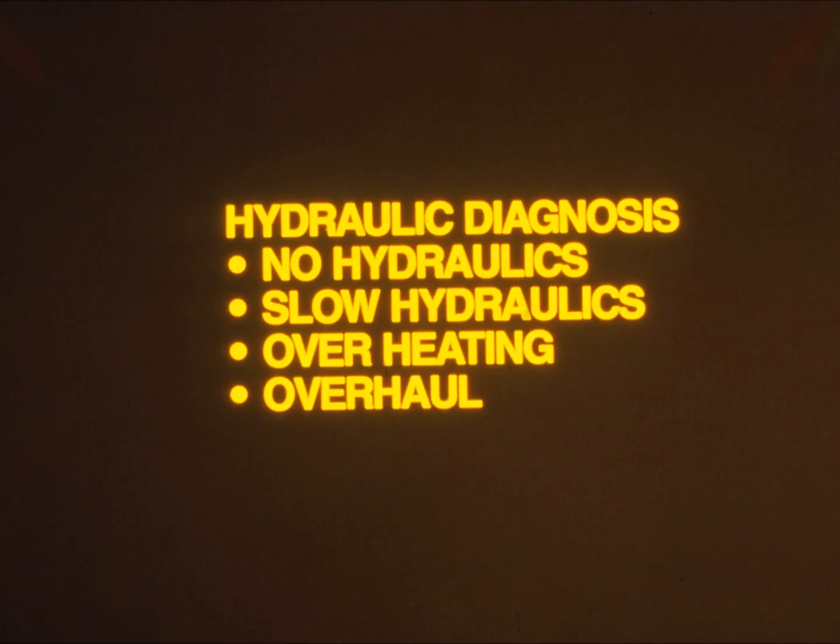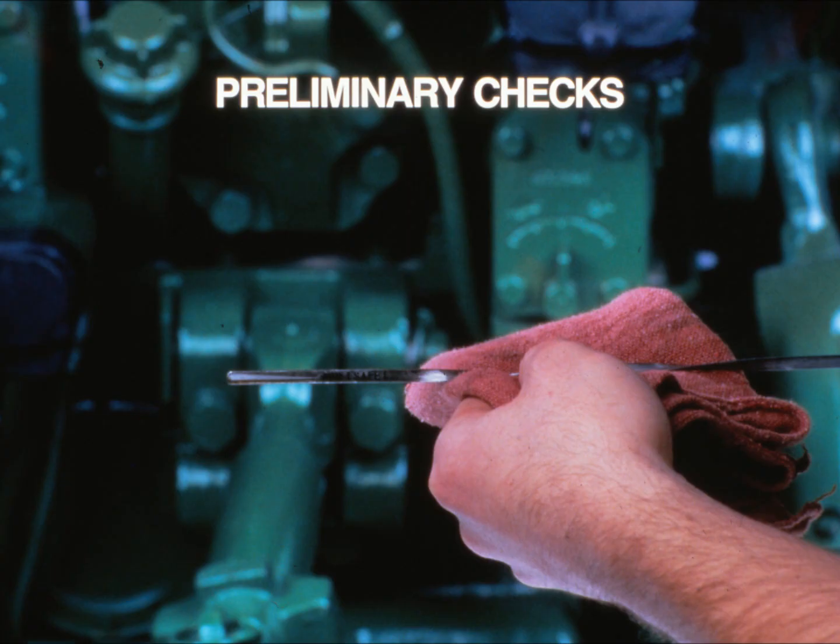When should you perform this diagnostic procedure? When the hydraulics are not functioning, when hydraulics are functioning slowly, when the hydraulic oil overheats, and after any major repair or overhaul of the hydraulic or transmission system. Hydraulic diagnosis begins with preliminary checks. These checks include talking to the operator, checking maintenance records, checking fluid levels, and looking for leaks.